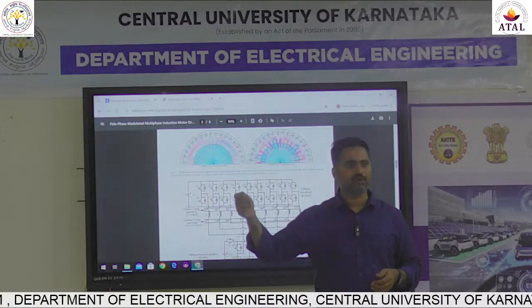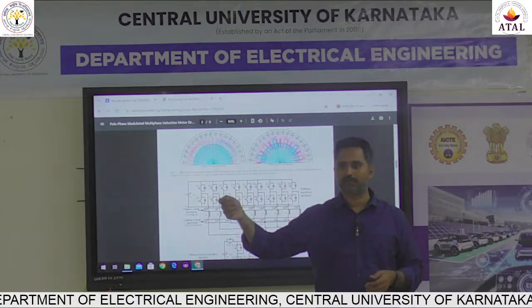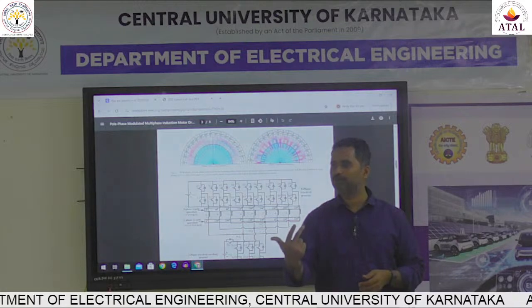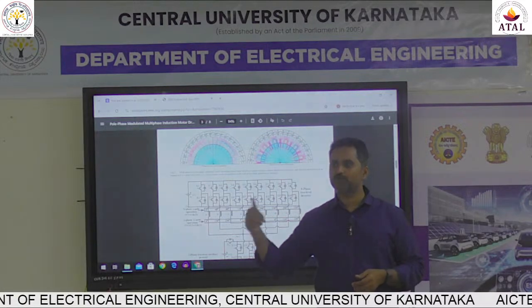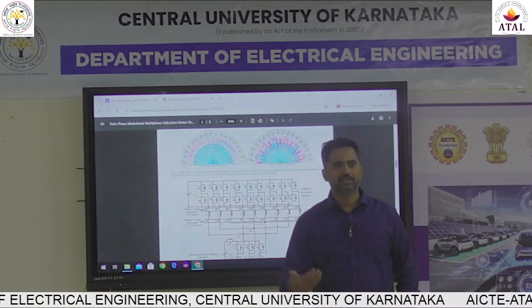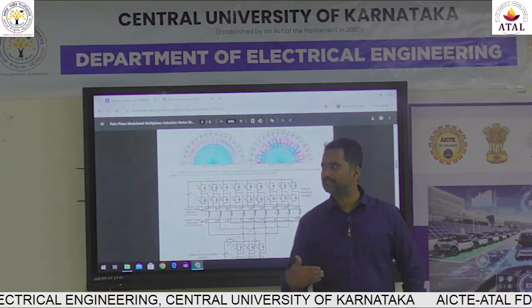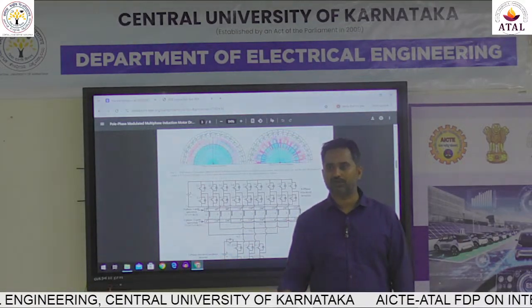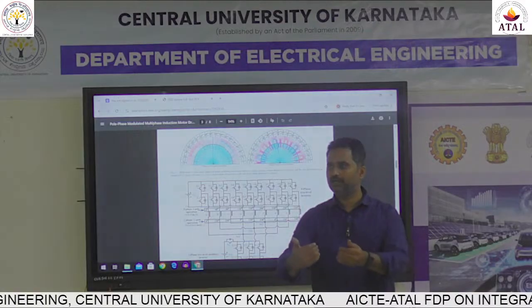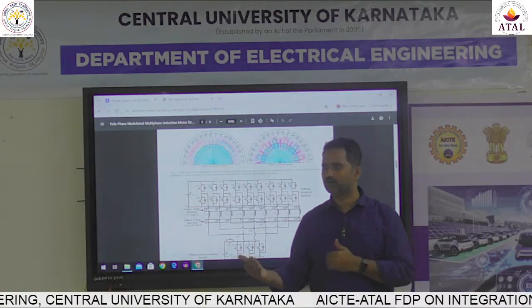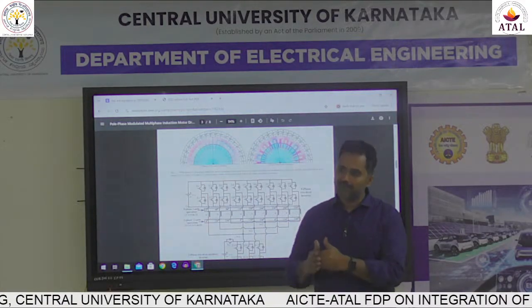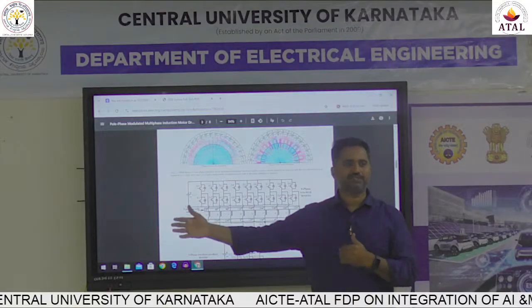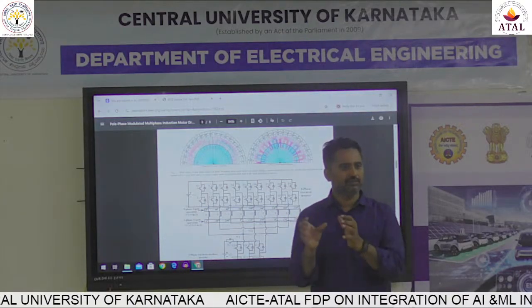The discharge will go all the way to 100 to 150 or 200 amperes, but charging will happen in only 1 or 2 amperes. Whereas your UPS or mobile batteries charge faster but cannot discharge faster. So typically these batteries are costly, where they charge faster and discharge slower. Similarly, at the other extreme, those that discharge faster are also costlier, so you have to be in between.